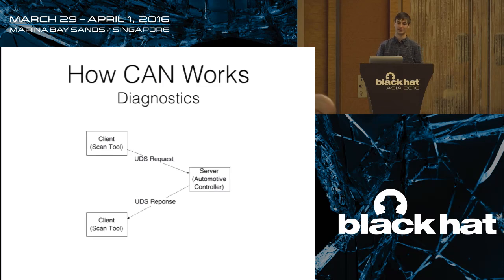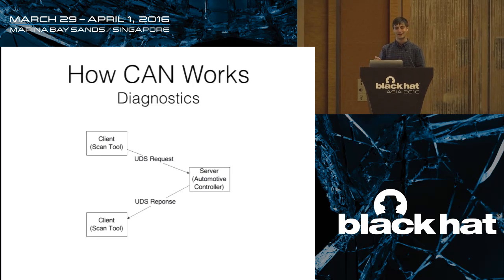You can get vehicle speed, engine RPM, airflow values. You can get temperature sensing, all kinds of information. It's all standardized. There's a great Wikipedia article that has every PID. It's basically the number 1 reference online for that information. But OBD, that's the limit. You can get fault codes, clear fault codes, that's it.